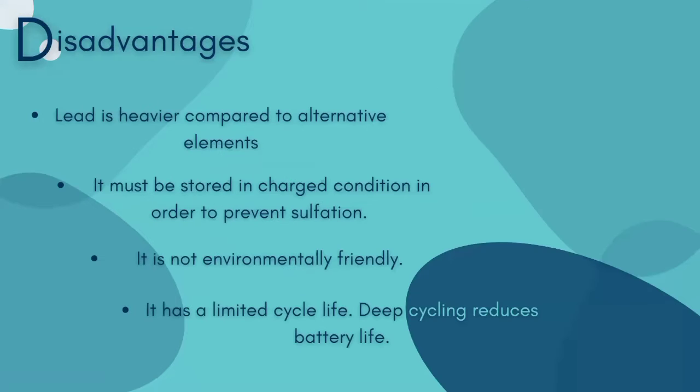Arya, please show the next slide. So here are some disadvantages of this battery. Lead is heavier than the alternative elements like nickel and cadmium. In fact, cadmium can be used as an alternative element, while lead is 1.32 times heavier than cadmium. It must be stored in charged condition to prevent sulfation, and it's not environmentally friendly, and we will highlight that in the next coming slides. And it has a limited cycle life.